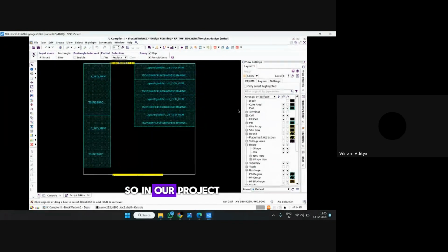In our project, we have six macros to place, and that placement should be done by our own thinking, so that the further steps are very easy, like placing our standard cells, called gates, and routing between the standard cells, without overlap or creating any mess or malfunction in our electronic device.